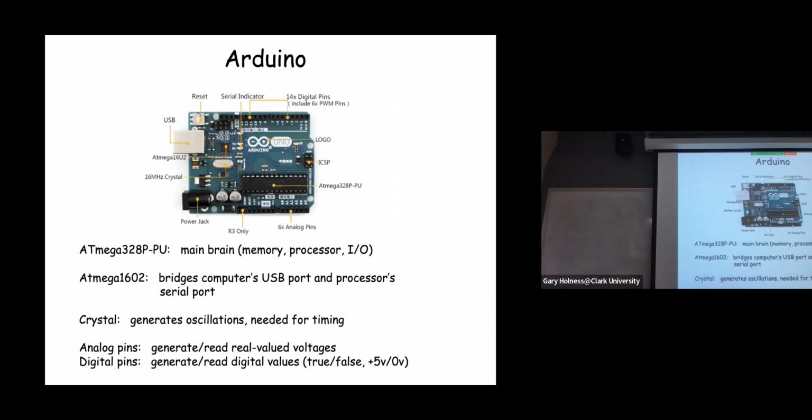Now, if you were to take a scope and actually measure it, it's not really 0 volts, it's effectively 0. It's like 0.3, 0.4 volts up to a threshold, but you can think of 0 volts as a logic false, and plus 5 volts, plus or minus some delta, is a logical true. And so together with the digital I/O pins, which are programmable as well, and the analog I/O pins, you're going to interface with various devices, namely your sensors and your actuators. Okay, any questions about this?